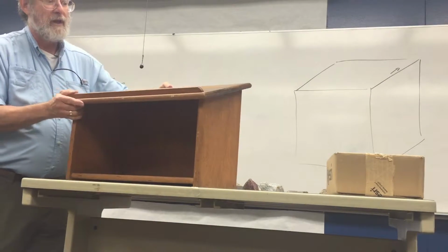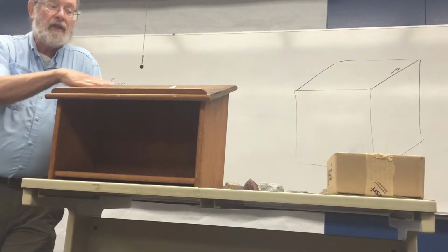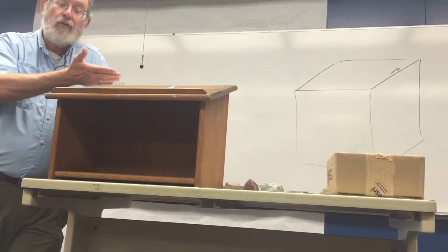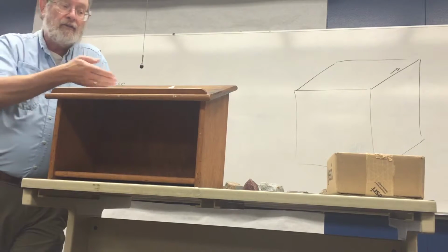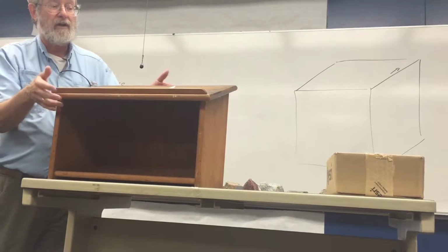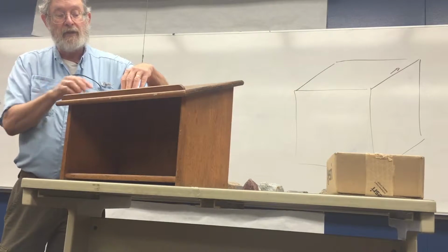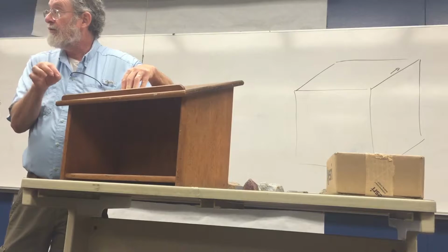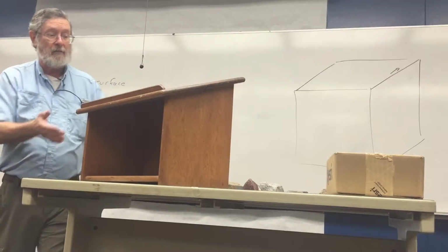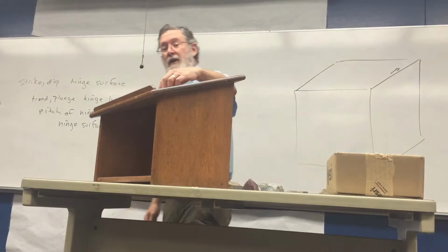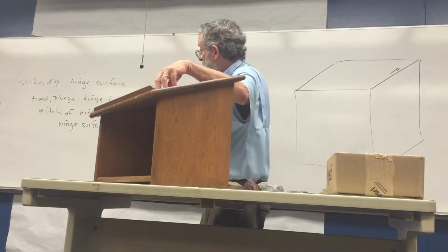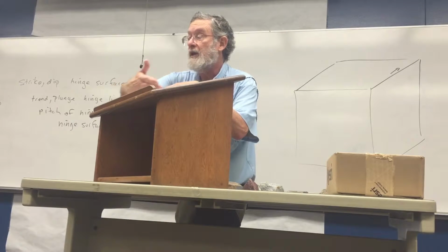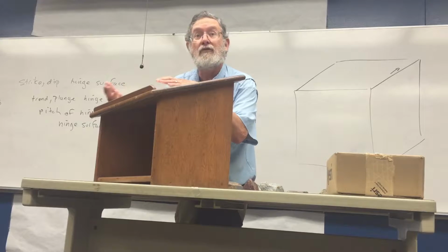By definition, if we have a plane, and this plane is inclined, our strike line here is defined as a horizontal line in the plane. Then we look at its orientation relative to magnetic north. So if we took, for example, something around in here, we would start off at north, and it looks like we would go about 45 degrees toward the west to define the orientation of that line. That would be the strike line.